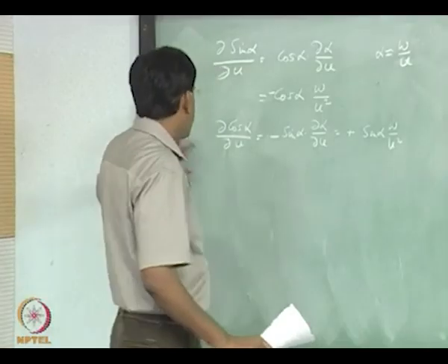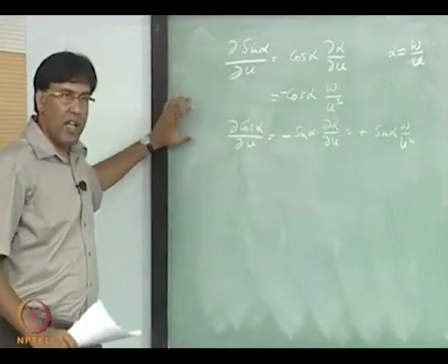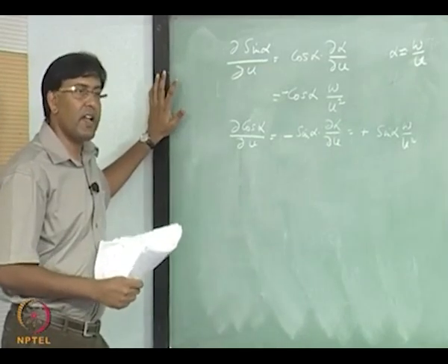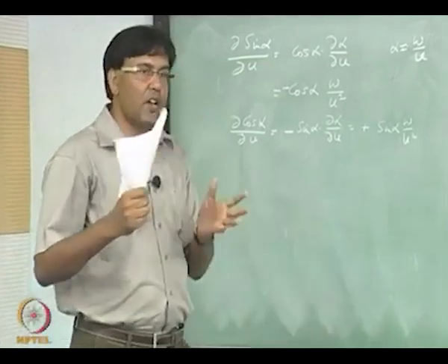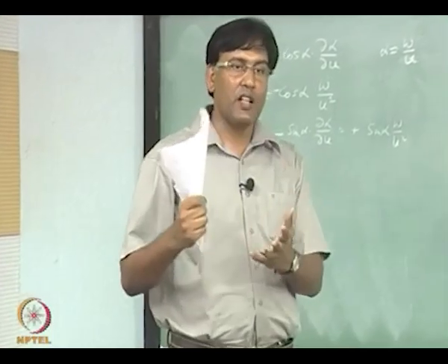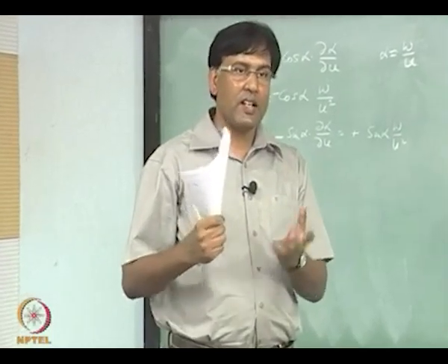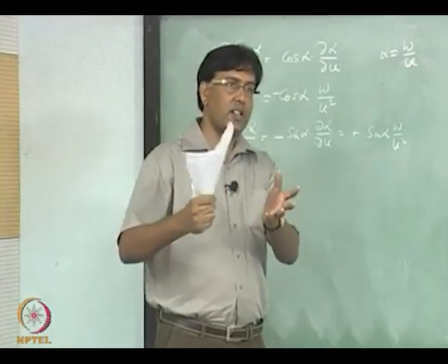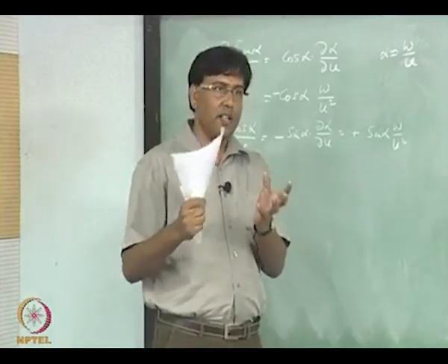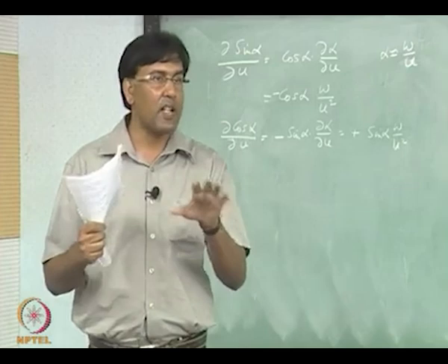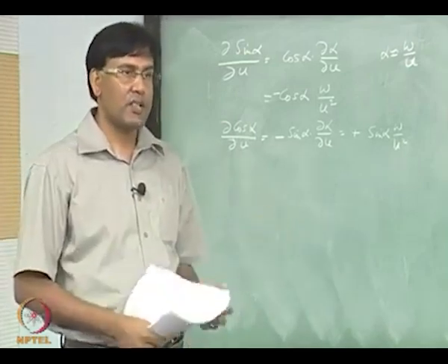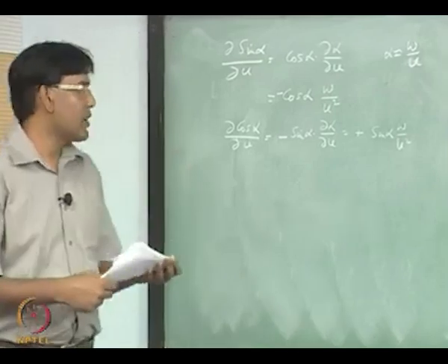So what you have is this, okay. Now as I said, we have to evaluate the derivative at the equilibrium flying condition, right, and actually that is how you are going to keep your model in the wind tunnel, isn't it. You are not going to give a motion to the model, you are just keeping a static model in the wind tunnel, and you are trying to measure the forces and moments, right.